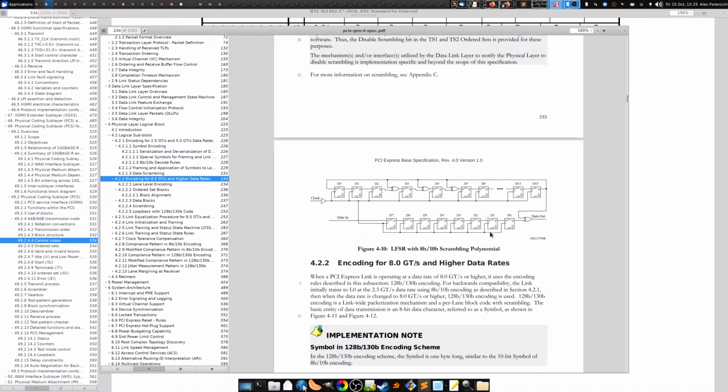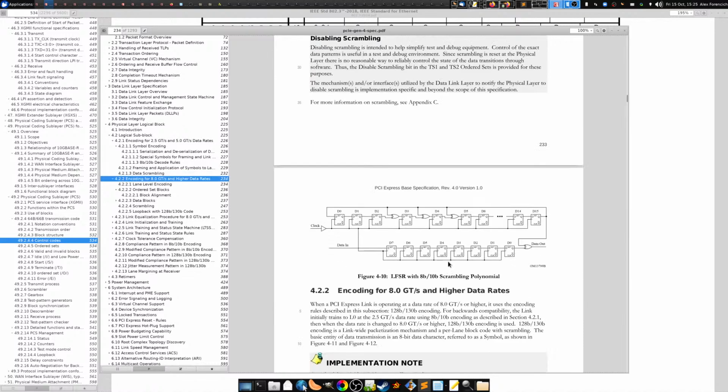I'm not sure what the story is with this delay exactly, but this is not a self-synchronizing scrambler. And I think they do that for bit error reasons, so you're not getting multiple bits flipped because of the scrambling. But this does mean that you need to do more work to bring up the link, and you need to synchronize the scrambler state periodically. And in PCI Express, all the links are in-system point to point, and there's a lot of negotiation that takes place between the devices at opposite ends of the link. So you can afford to do that.